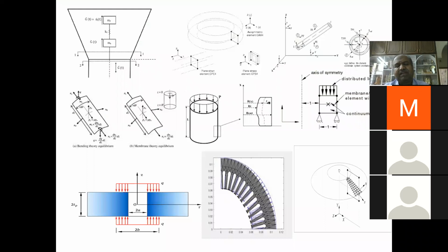We have a lot of applications of axisymmetry. You have flywheels, gears, cylinders, thin or thick, and then plates, cooling towers, nozzles. Many of the applications you would see, we'll treat with 2D instead of 3D analysis, because the solution is going to be the same, and it simplifies your calculation time.